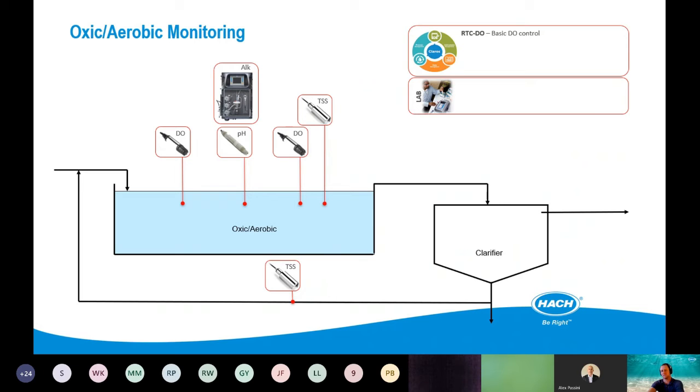And the idea here is that there are a number of controls that we use that are contingent on the solids concentration. We're using controls such as food to microorganism ratio that rely on this value. We're looking at potentially pounds under aeration, or even more specifically and more accurately, SRT.